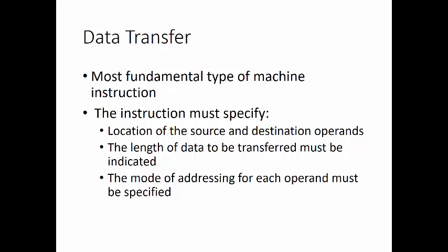If both the source and destination are registers, then it simply causes data to be transferred from one register to another, and that keeps it internal within the processor. If one or more of these are in memory, then the processor must perform some of the following actions. Calculate the memory address. If the address refers to virtual memory, translate from virtual to real memory address. Determine whether the addressed item is in cache, and if not, issue a command to the memory module to do that data transfer.